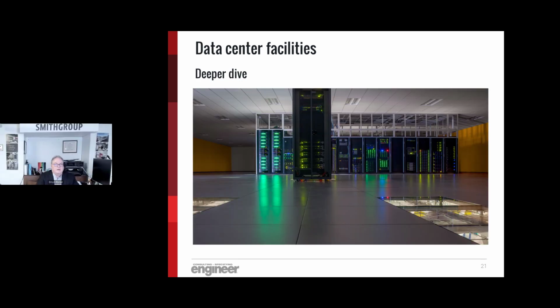Thanks, Zach. I noticed there were a number of people on the call involved in data centers, and I think there's an interesting example of the use of generators for mission critical loads other than legally required standby or emergency. Yes, there are emergency and maybe legally required standby loads in a data center, but most of these are considered optional backups under the code. But that still doesn't mean they don't have to meet the requirements we would like to have with emergency, such as 10-second startup times and reliability.